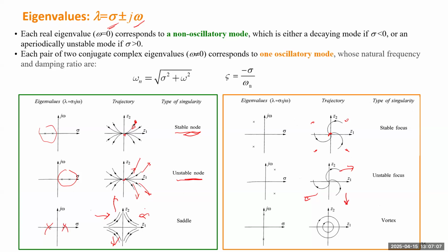And the last one is the marginally stable case. It's not unstable. It's exactly on the imaginary axis, which means if you start at any point, it will just stay on that orbit, a closed orbit surrounding the center, the origin. The amplitude is bounded. It's not really unstable, but it can be a marginal condition, which means in practice this is also bad, because any perturbation will cause instability of the system. So those are all the modes we have, but here we focus on those two possibilities.